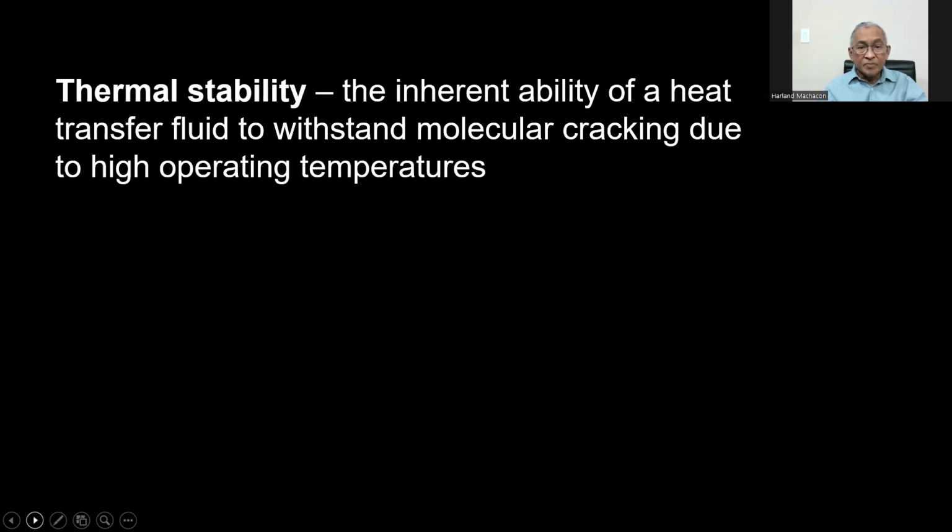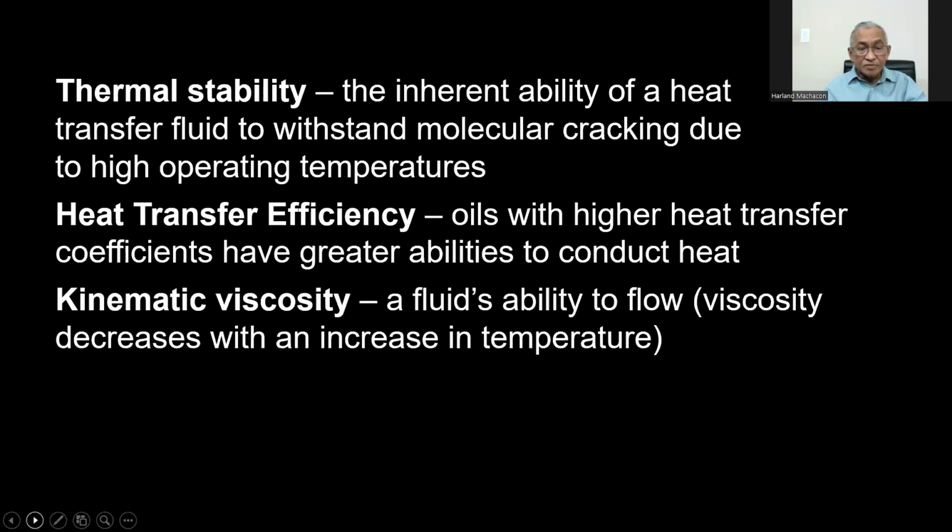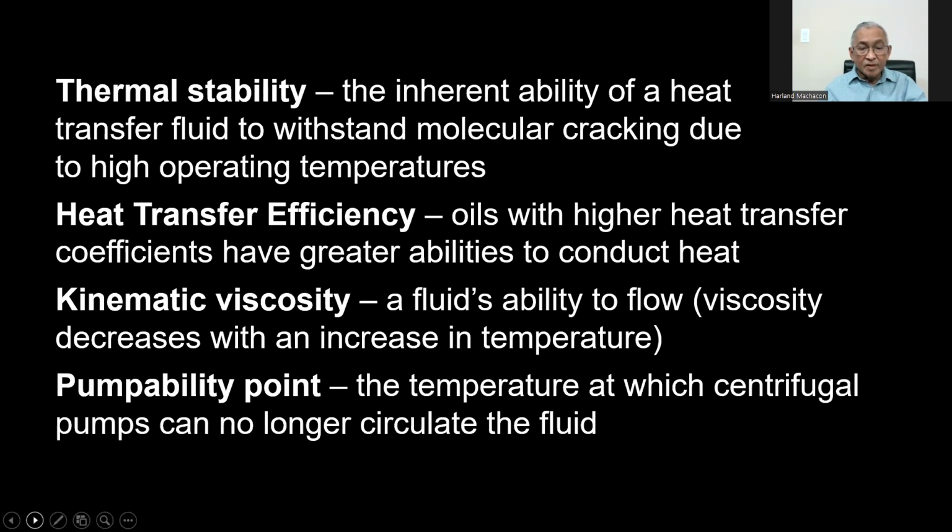Thermal stability is the inherent ability of a heat transfer fluid to withstand molecular cracking due to high operating temperatures. Heat transfer efficiency: oils with higher heat transfer coefficients have greater ability to conduct heat. Kinematic viscosity refers to the fluid's ability to flow. Viscosity decreases with an increase in temperature. Pumpability point is the temperature at which centrifugal pumps can no longer circulate the fluid.